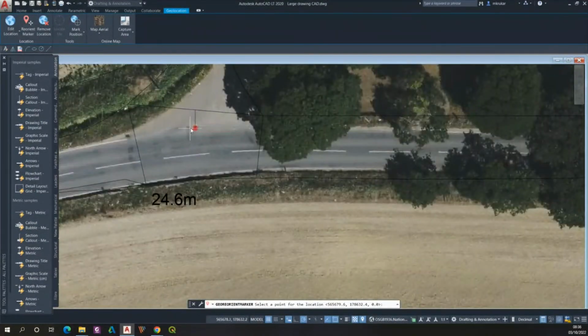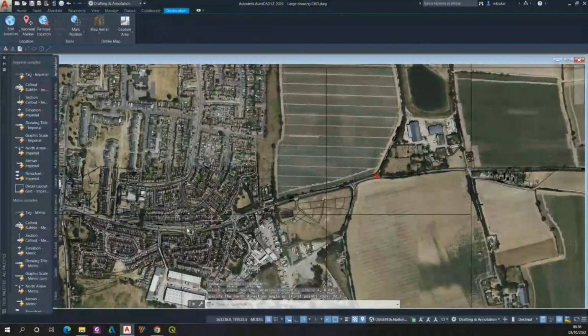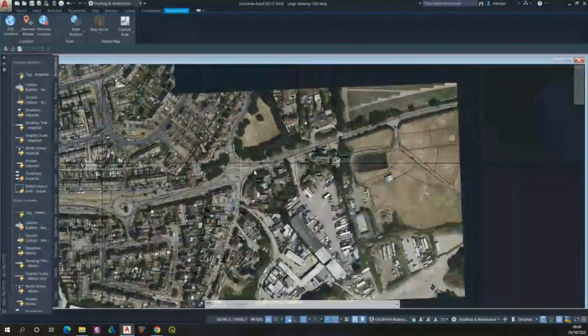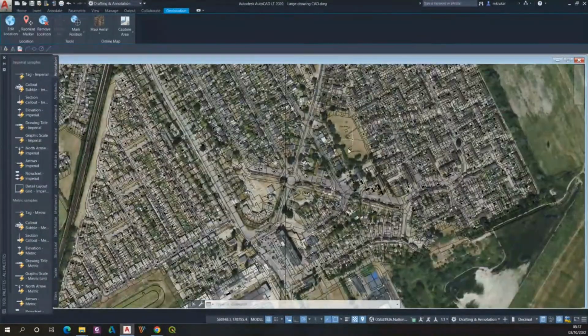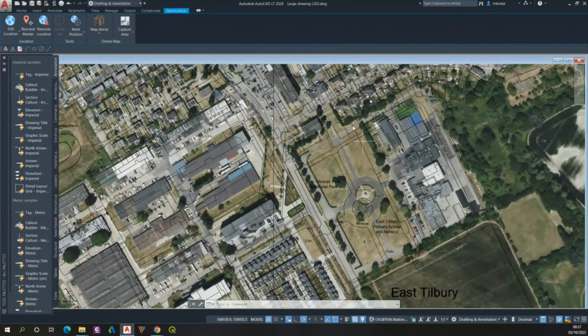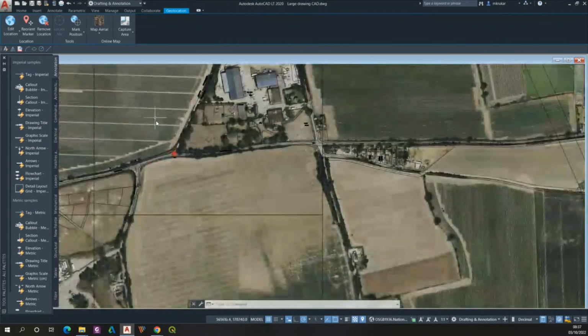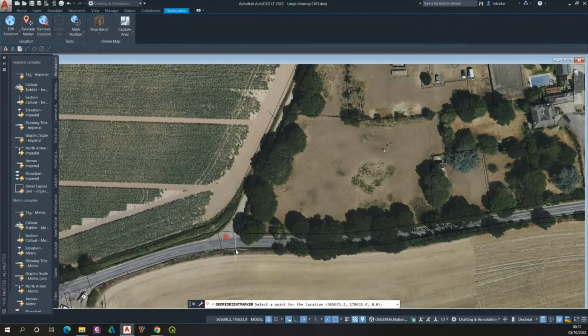Okay, so let me pull towards west, and in my north arrow we can use also decimals. So if you are unhappy with the orientation at this moment, you can use the decimals like 92.3 and try another method. And let's check what has happened. So it's still quite not right. So this is like the trial and error method. So after trying several times more, you will be sure that your map eventually is correct.